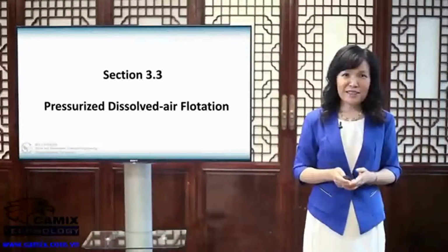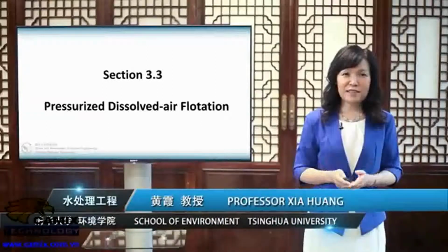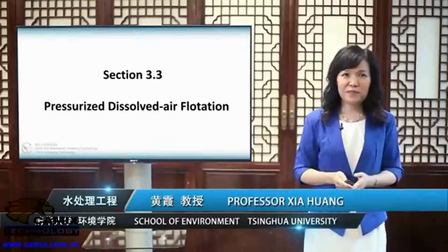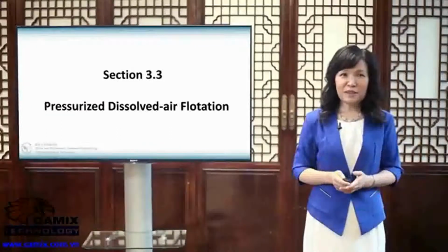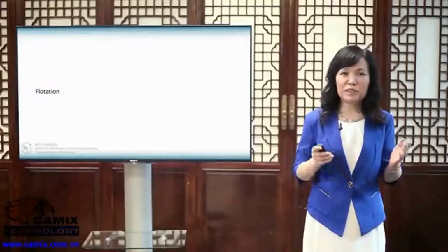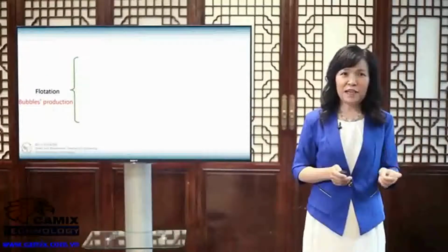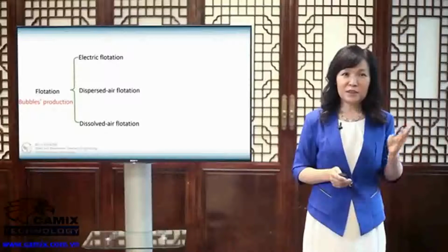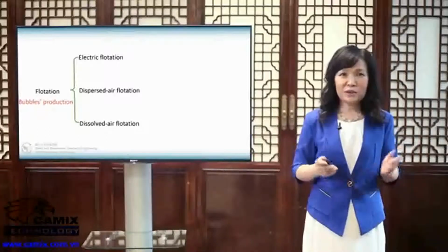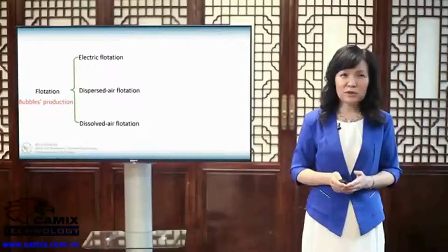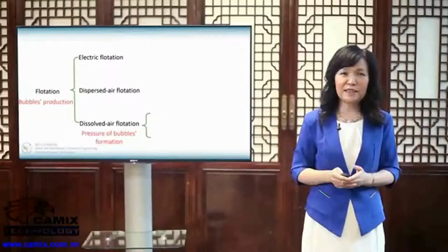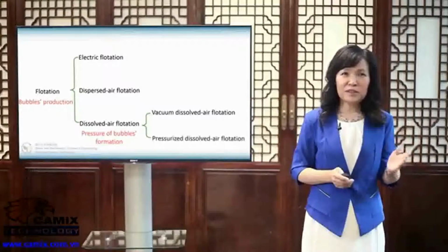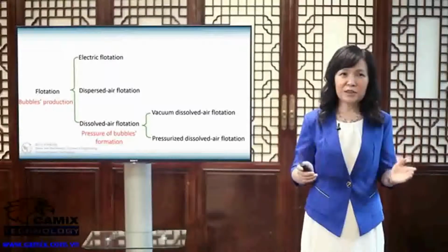Hello everyone, in this section I'll introduce the pressurized dissolved air flotation. According to the means for bubbles production, flotation is generally divided into electric flotation, dispersed air flotation, and dissolved air flotation, DAF. DAF can be classified as vacuum and pressurized types according to the pressure on bubbles in the flotation tank. Pressurized DAF is the most common flotation process, so we focus on it.